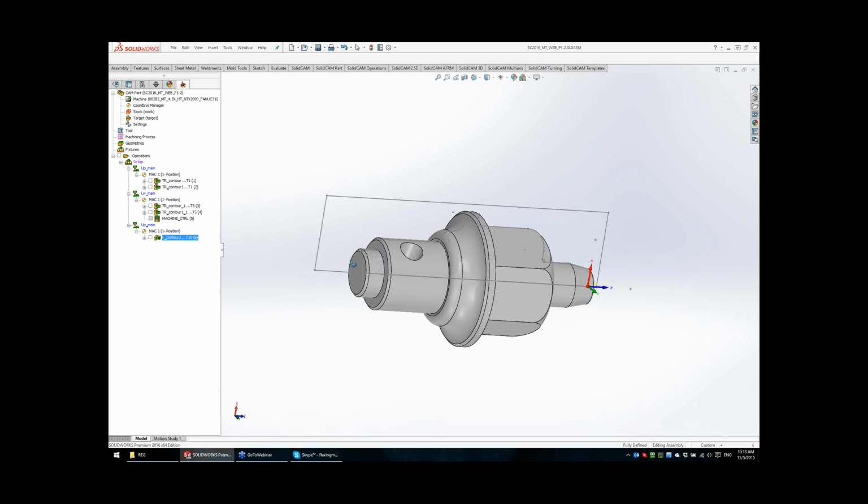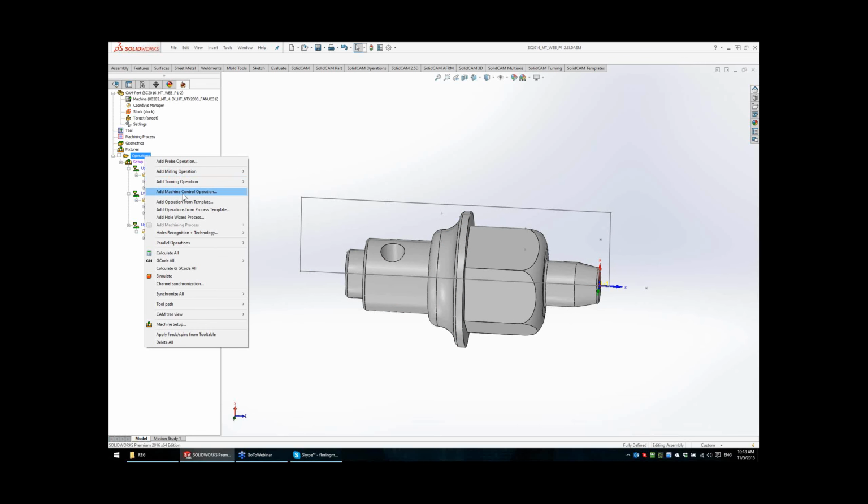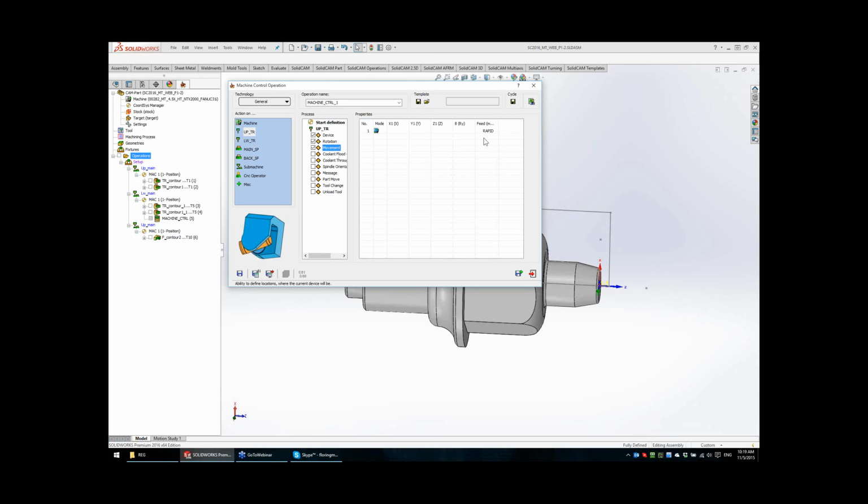Now, let's transfer this part to the back spindle. Again, I will add a machine control. Now, the last operation was working with upper turret on the main spindle, so I will send the upper turret to a safe position. First, the rotation of the milling tool is stopped. If I have a coolant activated before, I will stop the coolant and the movement.